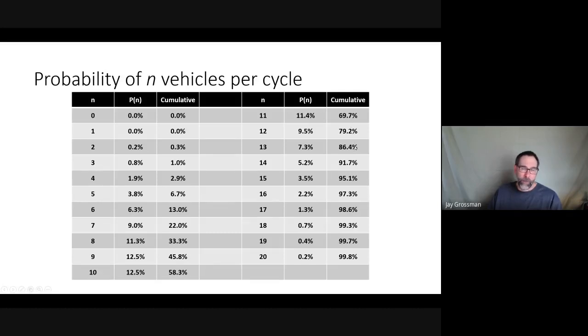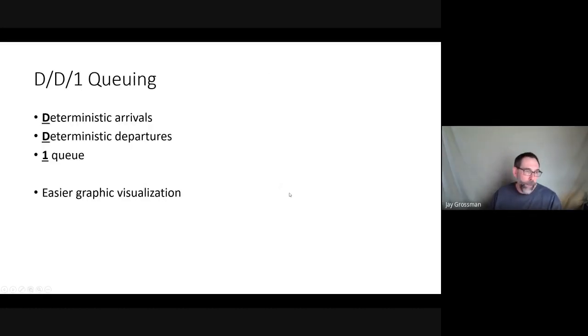It's kind of like what return period you're looking for in your storm, right? Do we want to be 85% confident we can handle as many cars as we need, or do we want to be 95% confident? For NDOT, they do their traffic analysis based on the 95th percentile. They don't want the 50th percentile. They want to be 95% sure that you have a long enough turn lane. So that's how we use Poisson. This is assuming random arrivals and assuming you know some average rate during the time period you're looking at, right? And those average rates change during the day, obviously. So that was Poisson.